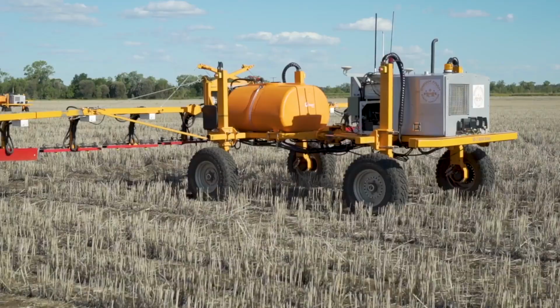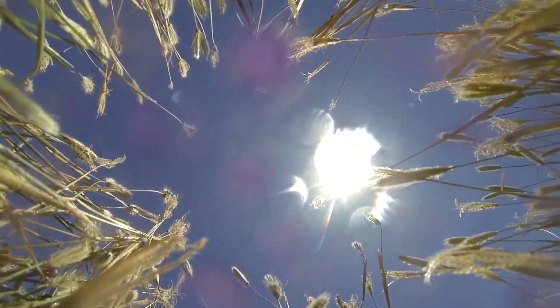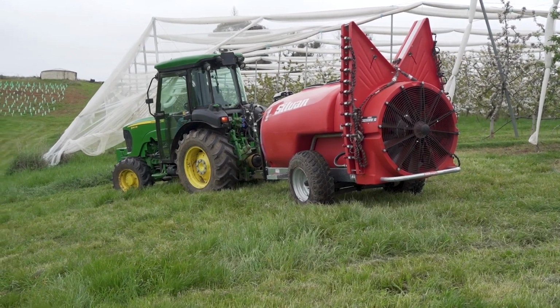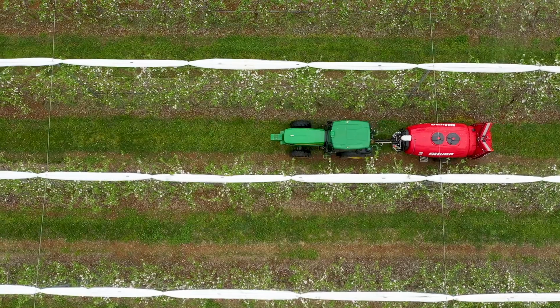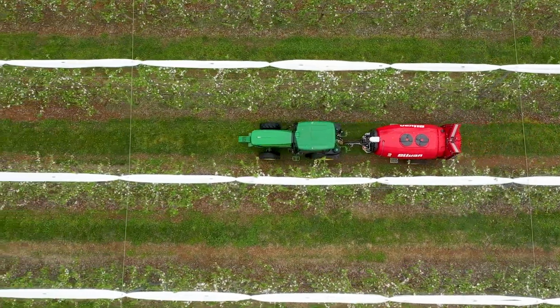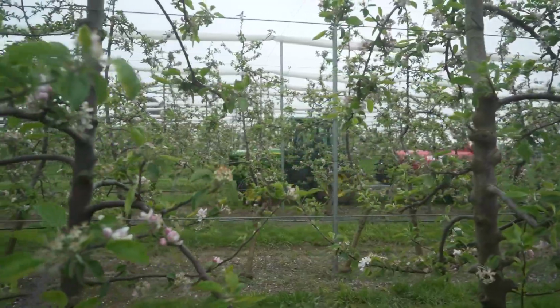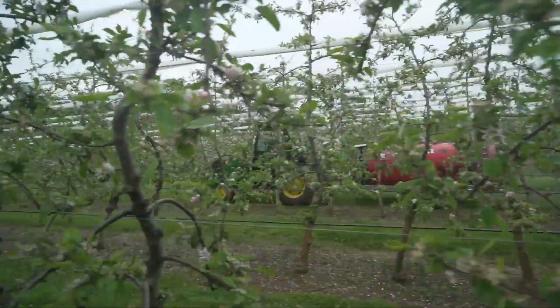As you drive over the ground, it'll turn on each nozzle as it needs to in the correct ordering. So if you have a small weed that you want to target, it would turn that particular nozzle on as you drive over that weed. What we've done is we've modified that technology, and instead of it being a straight boom on the ground, it's now a boom folded up in the air, and that's how we're achieving section control or individual nozzle control within an orchard. To the sprayer, it thinks it's targeting a 4-metre section on the ground, but as you drive through the orchard, that's actually reflected by the heights of the trees rather than the width on the ground.